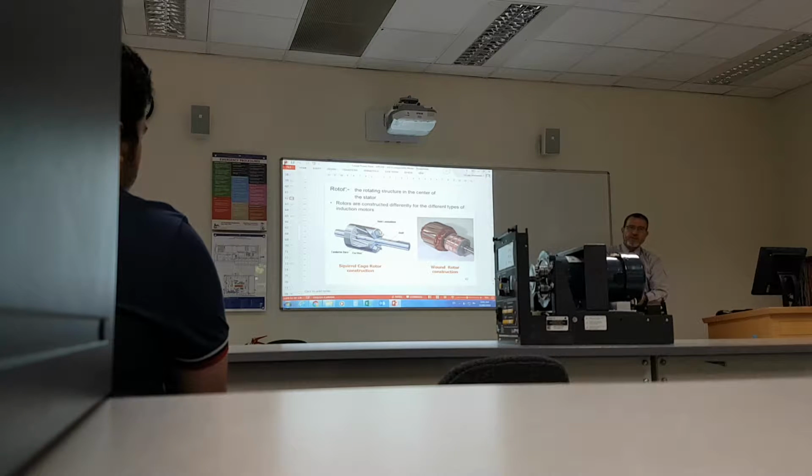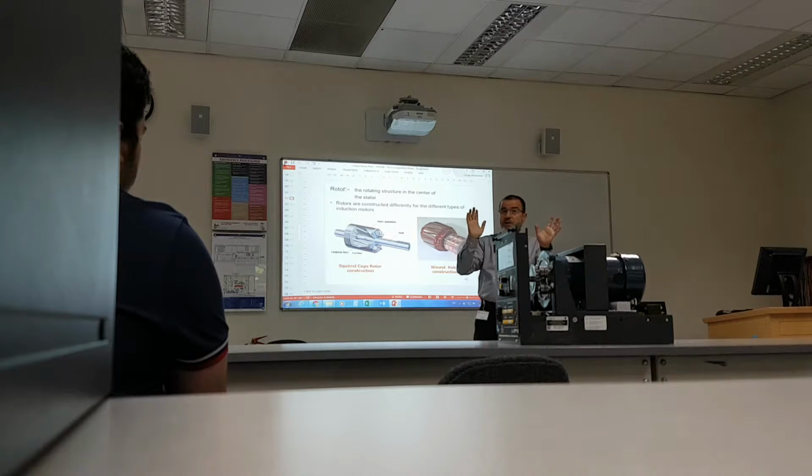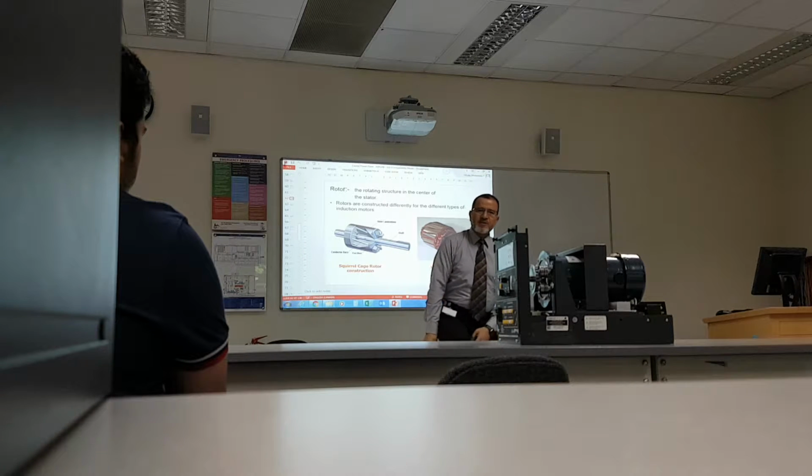It gets it going. Now, as it starts going, the difference of speed goes down, so the rate of cutting goes down. So the velocity V goes down, so the induced EMF goes down. It's not counter EMF, it's induced EMF. And it keeps doing that until there's just enough current to keep it going. There's just enough difference between the rotor speed and the synchronous speed to provide enough torque to keep it going without load. So what happens when you increase the load?